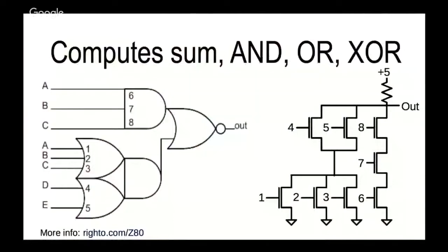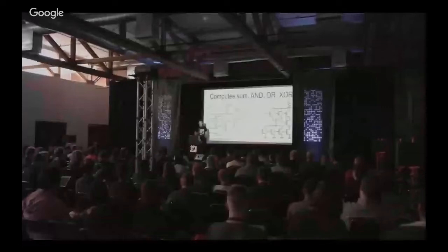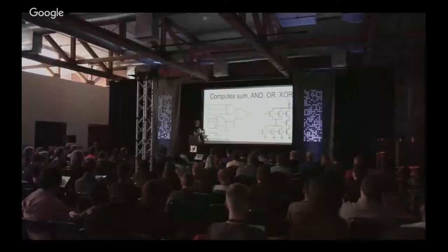These 2 gates, you don't require any circuitry. They're just made by wiring the 2 parts together. So this is one of the ways that made the Z80 much more compact. I won't try to explain what this is actually doing, other than it takes ALU inputs B and C and then computes the right operation, all with this one gate.